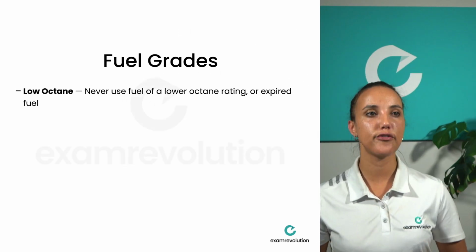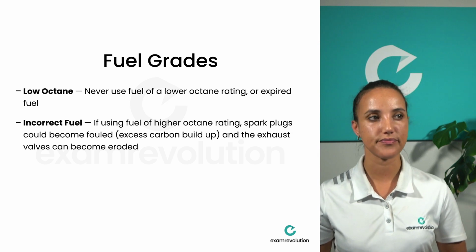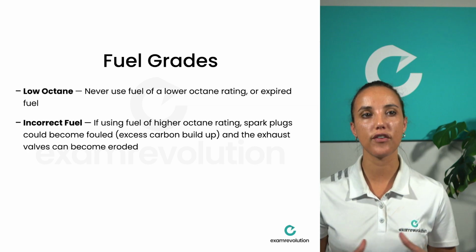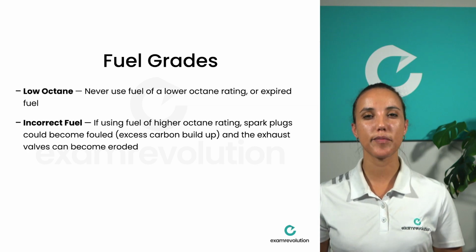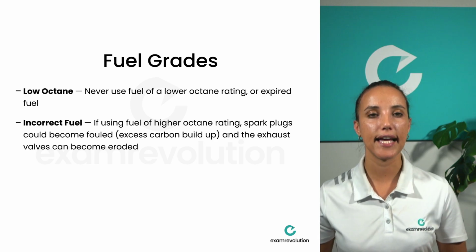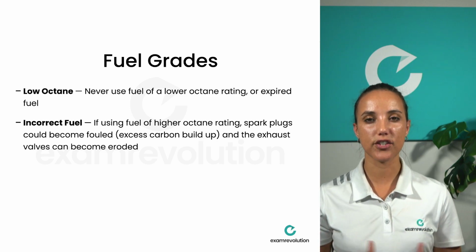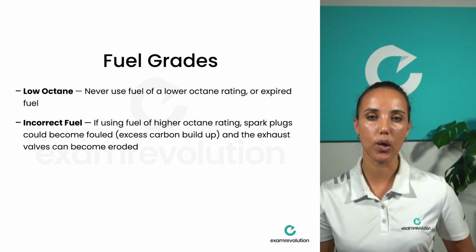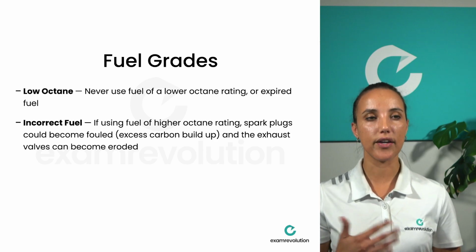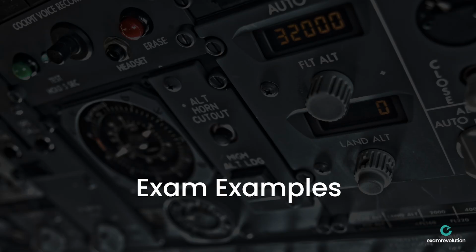So never use a fuel of a lower octane rating or expired fuel. If using fuel of a higher octane rating, spark plugs could become fouled because of the excess carbon buildup, and the exhaust valves can become eroded. So if you can't get the correct octane of fuel, never use a lower octane, rather use a higher octane. However, higher octane can cause spark plug fouling.